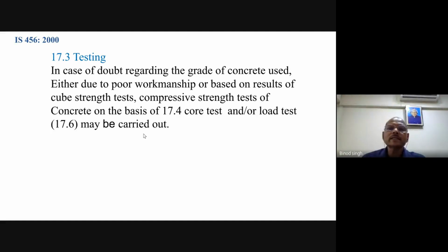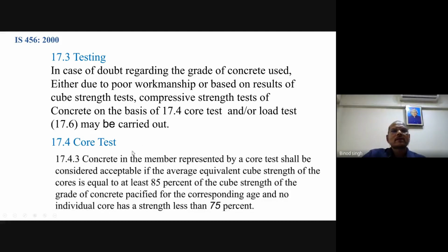And secondly, if it is a flexural member, then you can go for the load test that is given in 17.6. So we'll go for the core test. So what does it say about the core test? I am just reading the clause of IS 456. Everybody is familiar. If you go to clause number 17.4, you'll be able to see this.